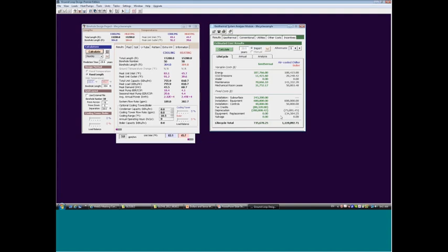And the net result is the net present value. Over 20 years, the geothermal system, all told, is going to cost about $735,000 to install and operate, all costs, all benefits. The conventional system is going to cost about $1.1 million. So it's savings of about $400,000 in your client's pocket, in today's dollar terms, for going geothermal in this example. We can go to the analysis tab.